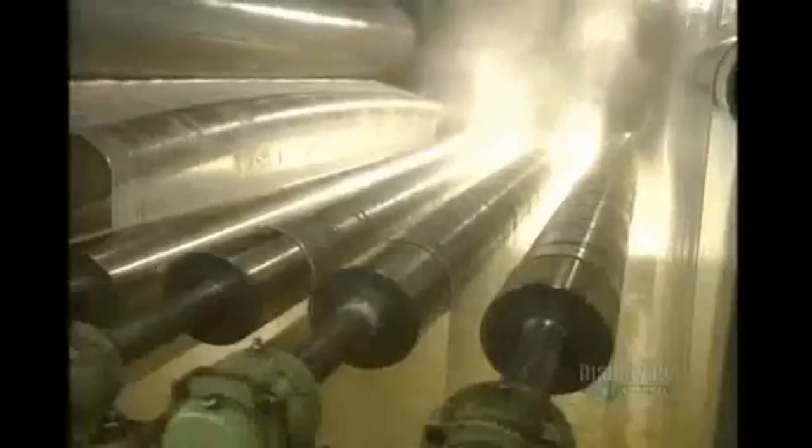Washing is done in a soapy solution at 80 degrees in a continuous manner at a speed of 60 meters of fabric a minute. The fabric is rinsed in clear water of about 30 degrees. Now it's on to dyeing. This is done with jets. Up to 12,000 meters of fabric are placed in clean water into which colorants have been added. The solution is heated and the fabric soaks here for about 6 hours. Then it will be rinsed in lukewarm water.